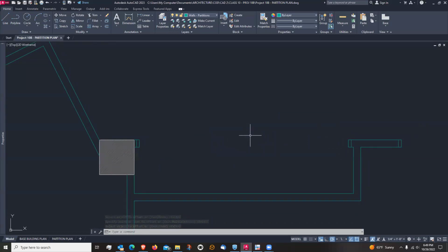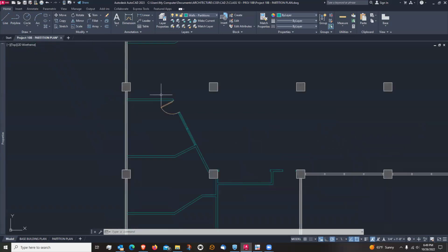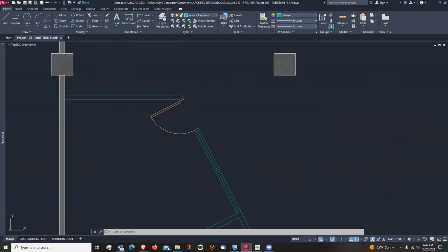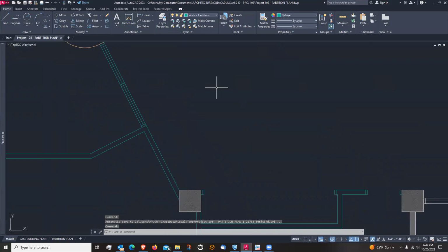All right. So generally speaking, a door thickness like this door here is 1 3/4 inch. That's a normal solid core wood door or hollow metal door, 1 3/4 inch thick. But when we're doing closet doors, that door can get really heavy. As you're sliding that closet door and you've got your briefcase and a backpack and your coat and an extra pair of shoes, and you're trying to slide the door and it's really heavy, right?